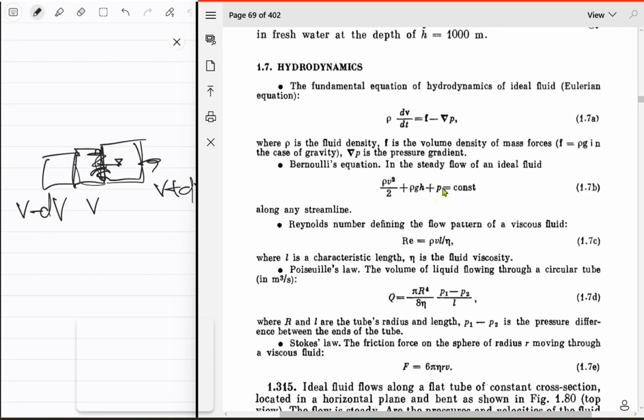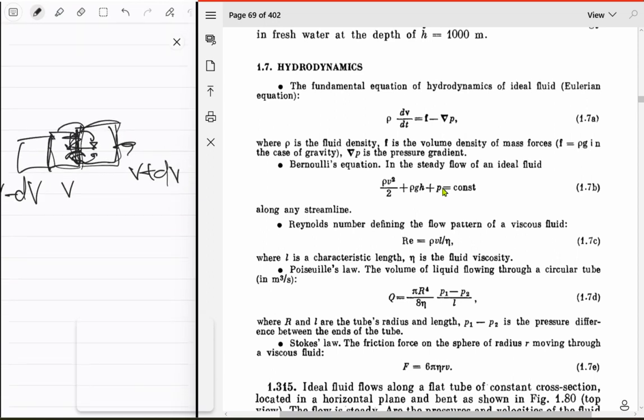So when you exchange, some of the higher velocity molecules go into this, and the lower velocity molecules come into here, which slows this down and speeds this up. Talking about the average velocity, it increases the average velocity of this block, and it decreases the average velocity of this block. And that's why you have viscous force, right? And when we say pressure, that is different from this phenomenon, right? Pressure is basically because collisions are happening. So that explains it.